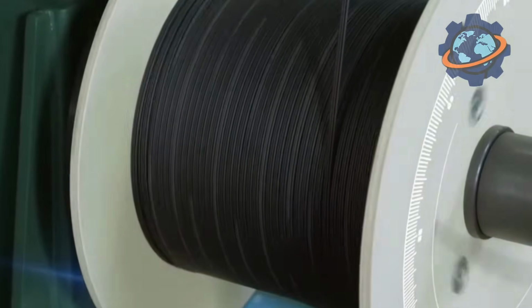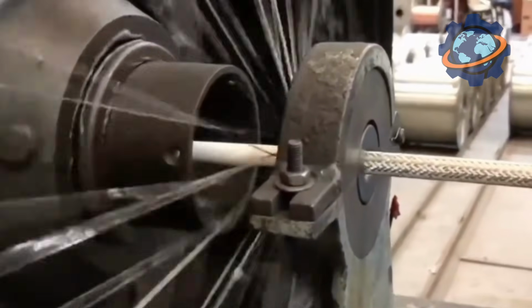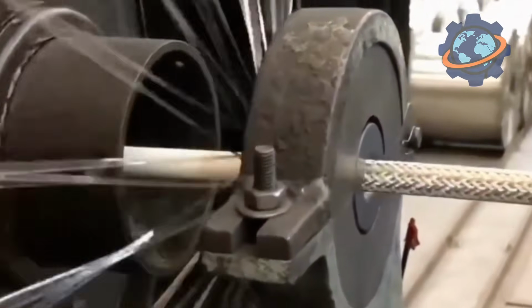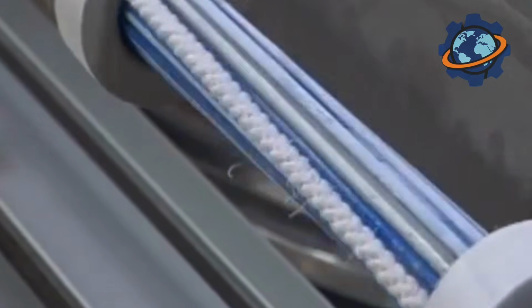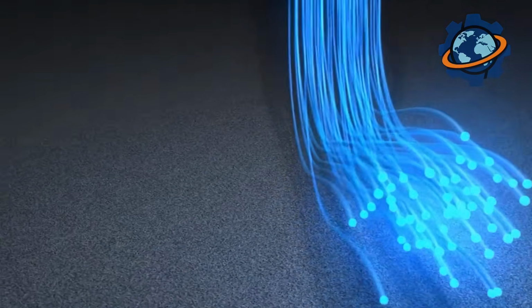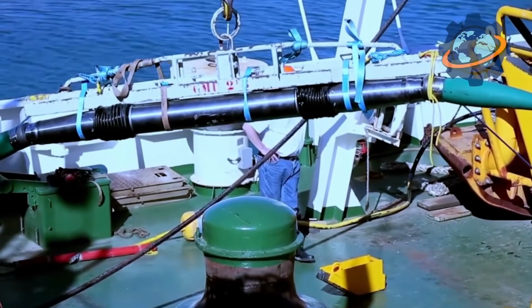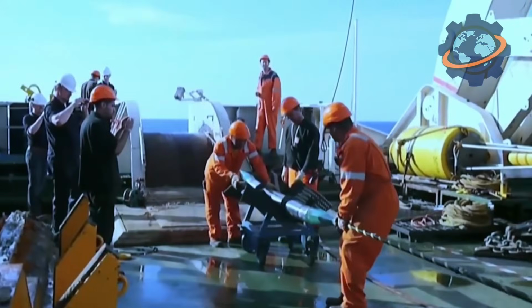Around the buffer tubes, strengthening elements are added. Fiberglass or Kevlar, very strong threads that protect the cable from stretching. Metal wire, for additional mechanical strength or grounding. A central strength member, a rigid element in the center that maintains the cable's shape. These reinforcements are needed so the cable can withstand tension, impacts, bending, and remain intact for decades.